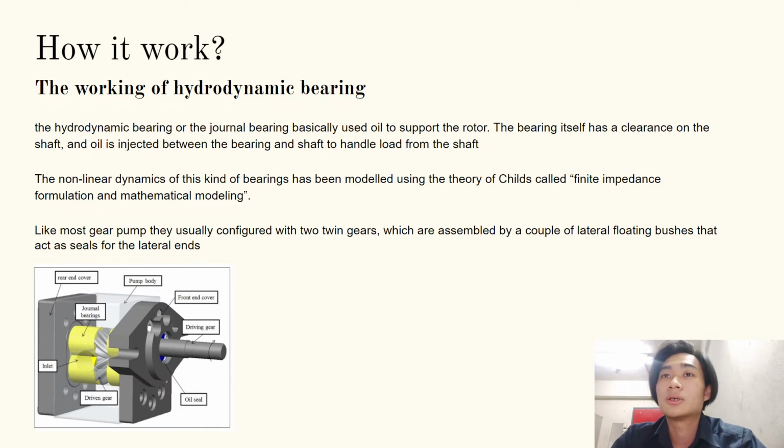In our case, the pressure comes from the pumping of the fluid into the pressure chamber. For your information, the radial force is generated by the effect of high pressure hydraulic oil on the surface of the gear, and the number of teeth in the high and low pressure zones must therefore be determined. The zones of high and low pressure depend on the outlet, inlet, and the chamber.